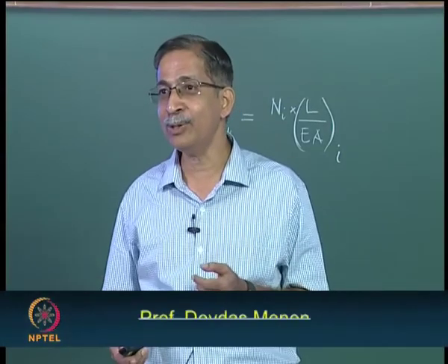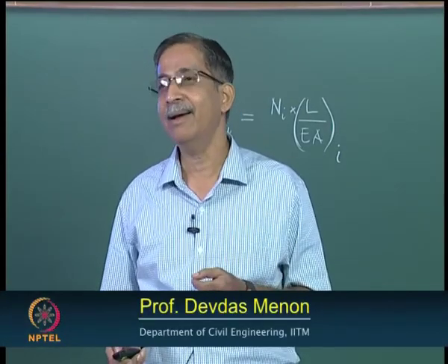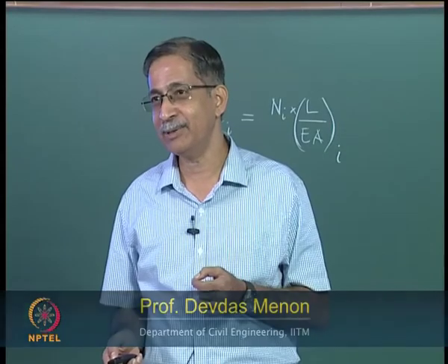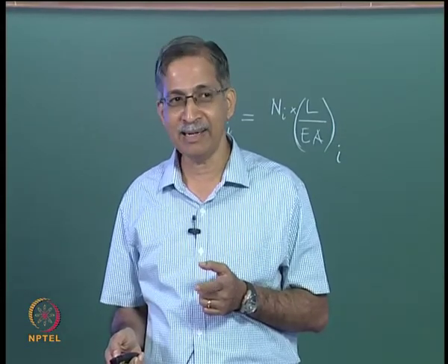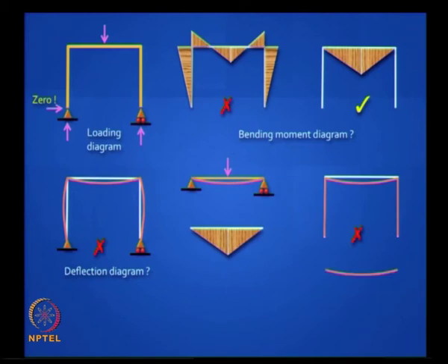Then what should you do for the vertical elements? Yeah, you preserve that. So this is wrong, because this would be violating the 90 degrees. So you have to draw like this, which is still feasible because the roller support allows a movement. So if your original shape was this, a student who can answer this completely is a rare student.